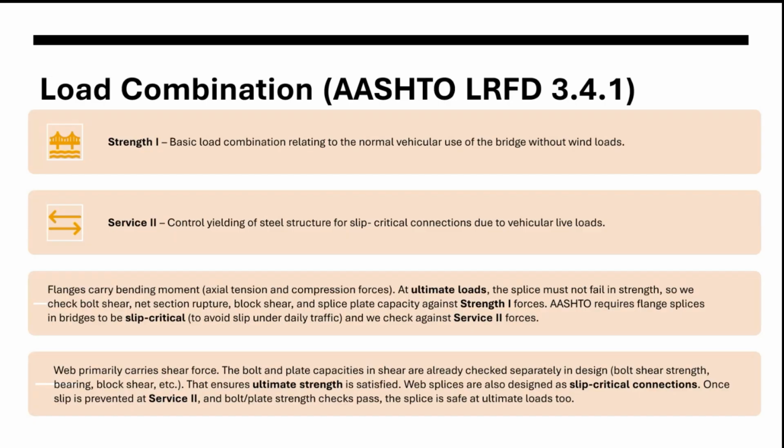And the second one is the Service II, which controls the steel structure for slip critical connection. So basically, we are using the bolts for joining the steel members. So the Service II load combination plays a major role in the design of the splice.